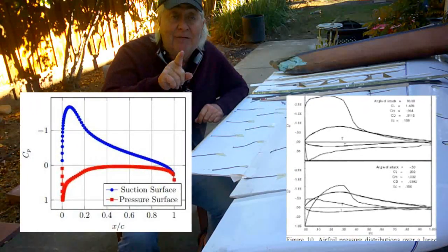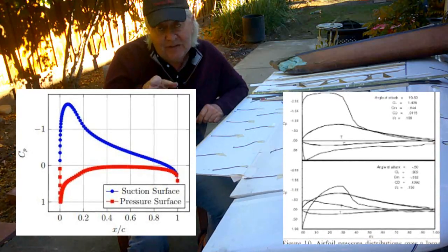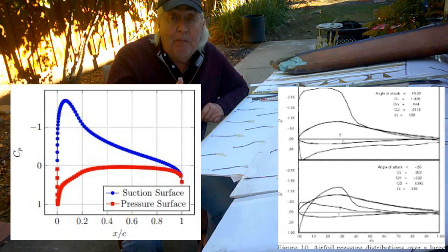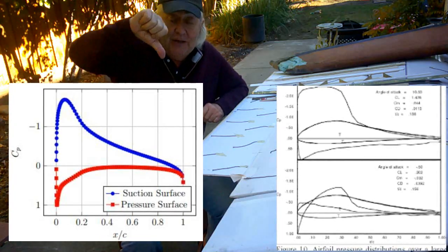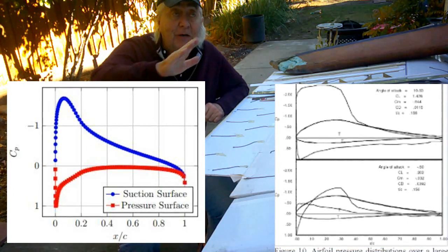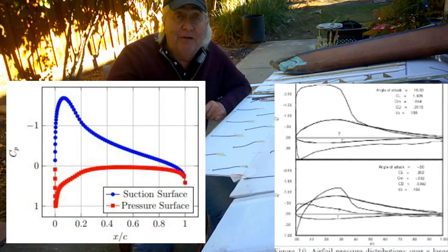And we call that the adverse pressure gradient because it's downhill. But you got to understand that these plots are flipped over. Minus pressure is up, positive pressure is down. So we're going from low pressure to higher pressure in a linear fashion. That's an adverse pressure gradient.